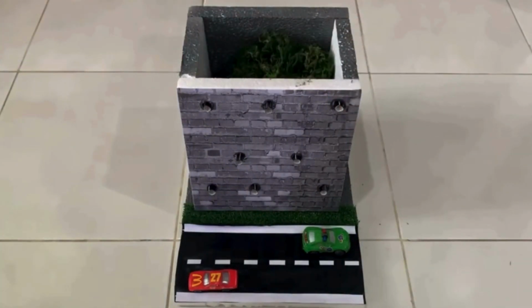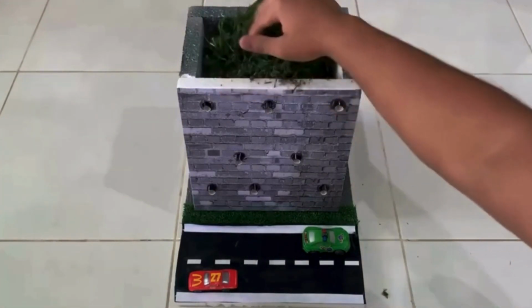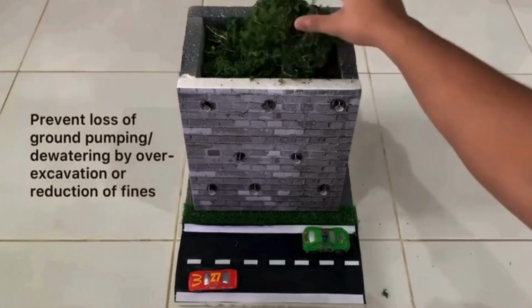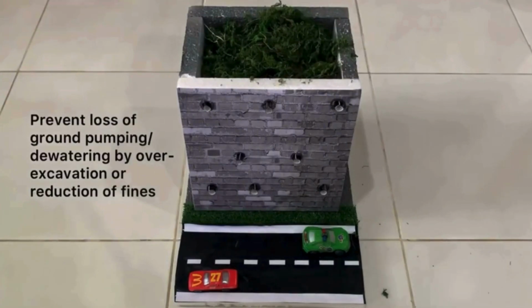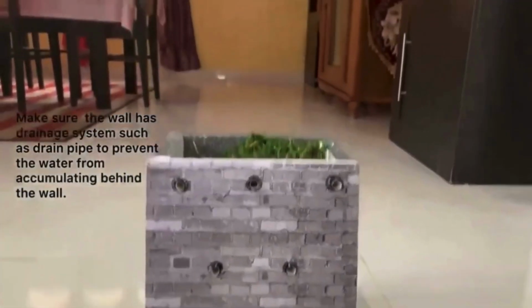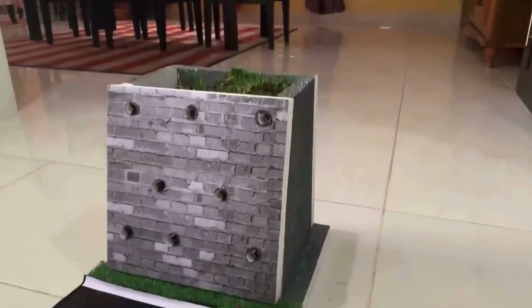We have identified some of the improvements we can do to our retaining wall. Firstly, ensure the wall has a larger base in order to accommodate the high ground loads. Next, prevent installation with unnecessary vibration, underfill failure factor. Third, prevent loss of ground by pumping or dewatering, over excavation or reduction of fines. And lastly, make sure the wall has drainage systems such as drain pipe to prevent the water from accumulating behind the wall.